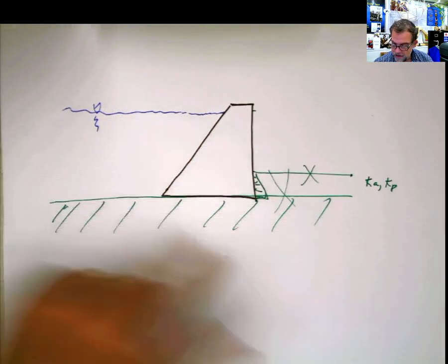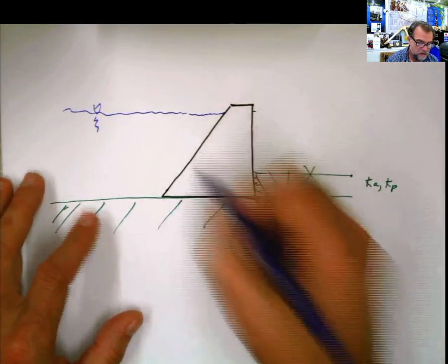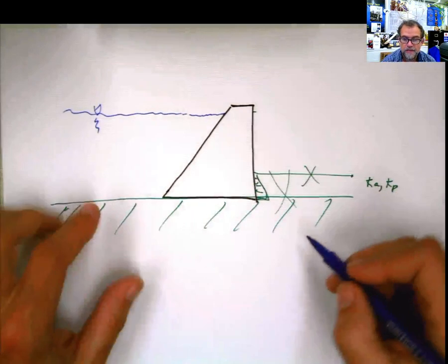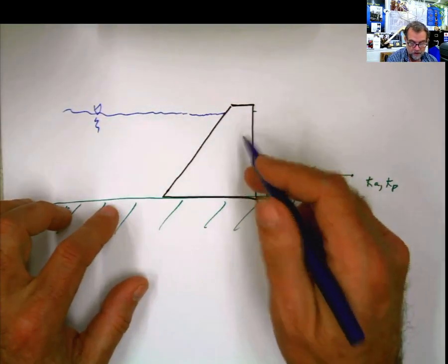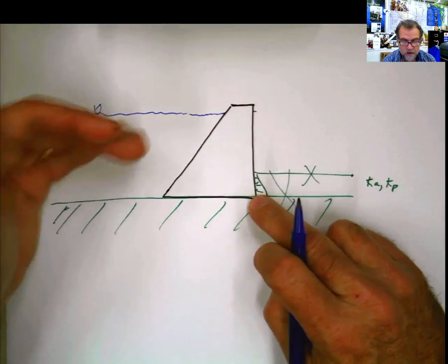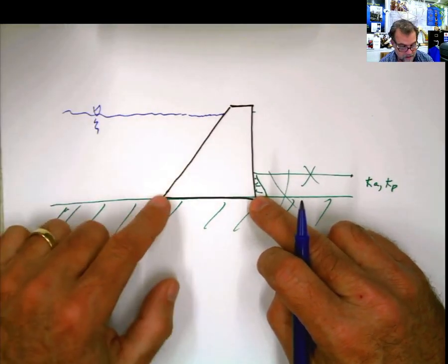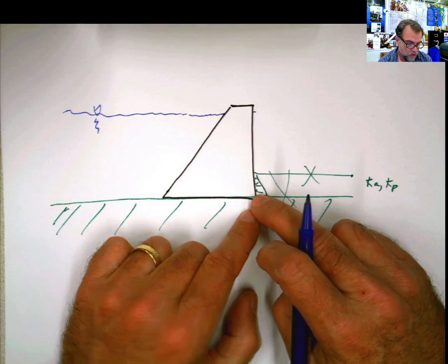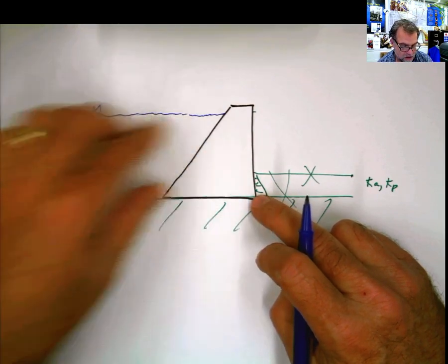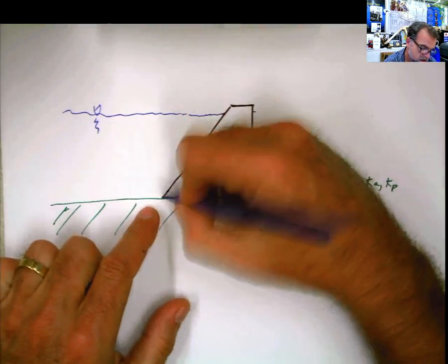But just imagine that you have this part here, and you have to calculate the resultant force or see how this dam can fail, forgetting about the earth. Well, this dam could fail if the pressure of water is big enough to do two things. First, it can slide it, and that could be easily studied if you want to, because if you apply the pressure here, it's going to be a horizontal force. What is going to be the horizontal force? Let's study this.